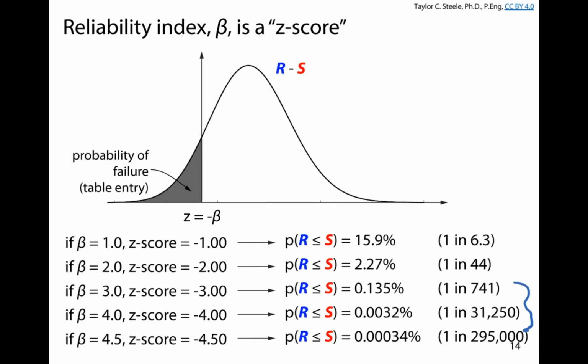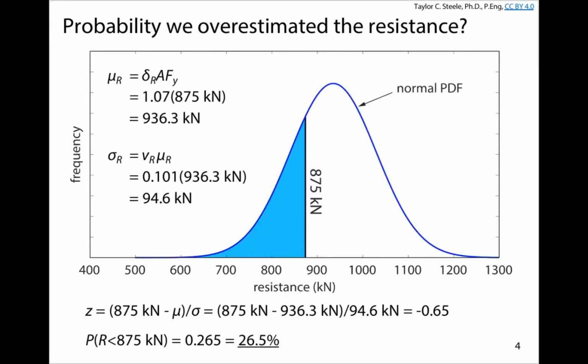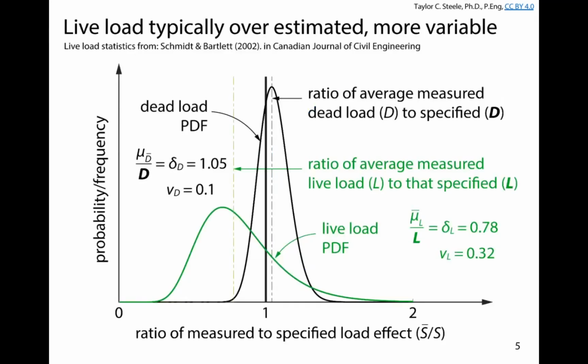Well, we already said before, there's a probability, and I'm throwing these back to slide 2. This is not the next one you'll see, but we have a reasonable probability that we're going to be overestimating the resistance. And so what we're going to do is factor down our estimate. Whatever our estimate is, let's say 875, we're going to factor that down by 0.9, and it might look something like that. And if it's possible that we're going to overestimate the loads, we're actually going to bump up whatever it is that we think we're calculating so that we're playing somewhere out in these ranges.